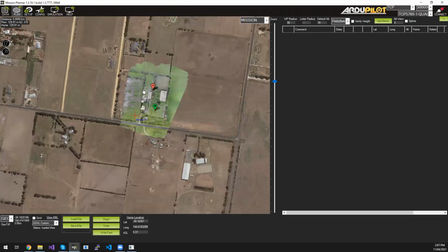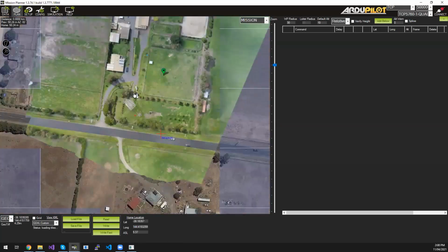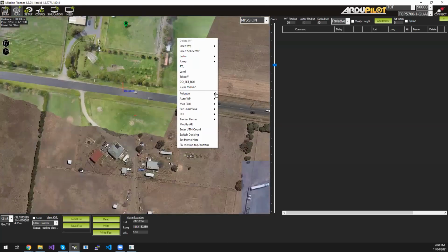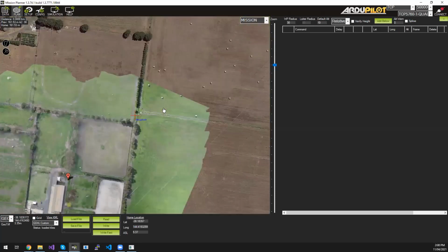Because I had that geo-referenced TIFF, which was actually referenced in geographic coordinate frames, all the images have been reprojected to geographic, which just means it's been reprojected to latitude and longitude. So pixel density is based on latitude and longitude, not UTM or some other projection. And we can see that. This data was captured by a GoPro on an old Solo, so it gives you a rough idea of what's capable.